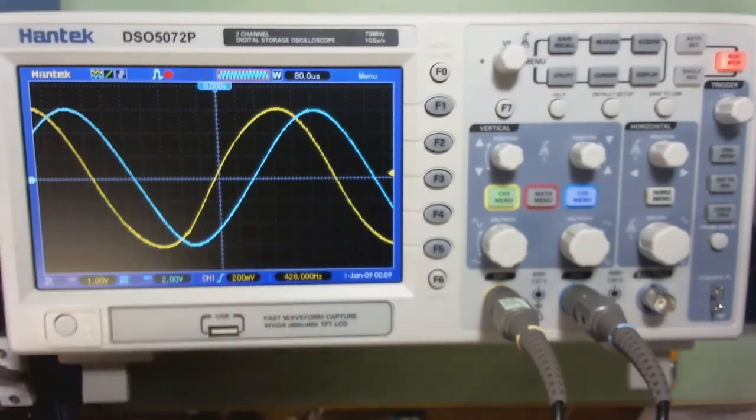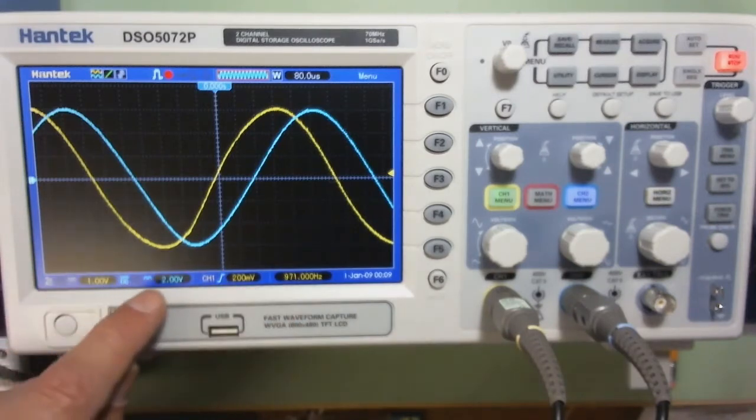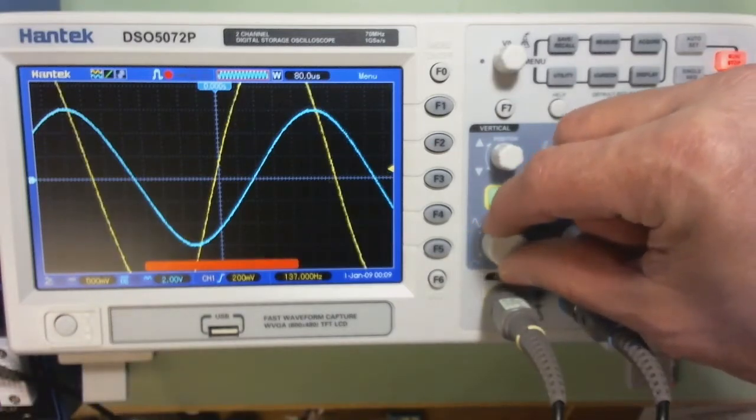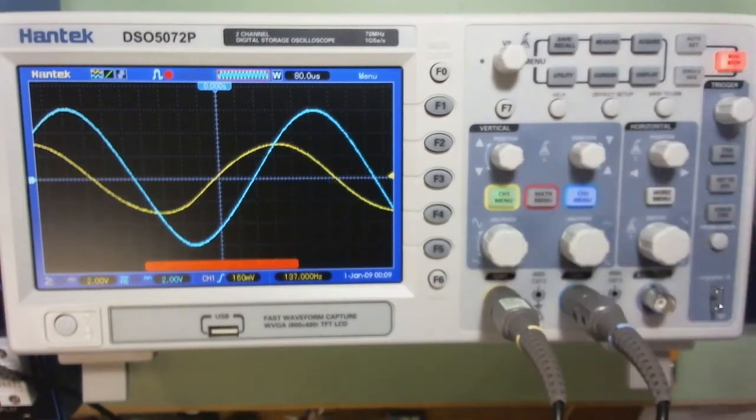Well, they're not the same at all because one is 1 volt per division, the other is 2 volts per division. So if I get this now they're both 2 volts per division, so I can compare them on face value. And again, if you have a very small signal, sometimes you will have these set differently, but you need to be careful and be aware of that.